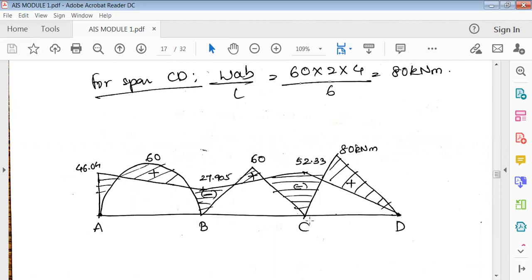Now wherever there is space, above the point A, go on marking this, and just hatch this like this. These are all negative bending moments. Negative bending moments will occur at the support, exactly at the support, whereas positive bending moment will occur under the loads. So these are the loads. When you draw this, whatever is above this line, the fixed end bending moments, all those bending moments are positive. So I've hatched it here and shown it as positive. Here also it is above this line, so it is positive.